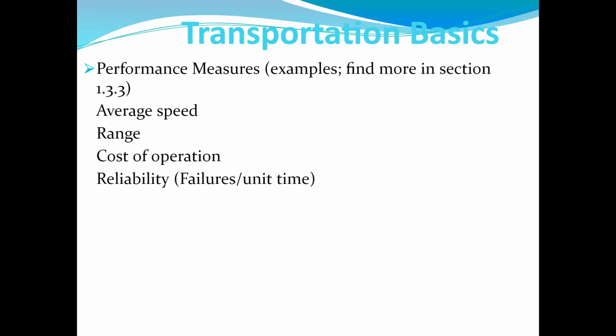So for example, even with the prevailing design philosophy, we allow for failures for 30 hours of the year because we design it for the 30th worst hour of traffic over the year-long period. And even that philosophy, as I said, is evolving now to be, maybe we shouldn't design it for even the 30th hour, because that still might be a little bit of an over design that leads to higher speed and less safe operations during other hours of the year. So these are interesting things that we'll talk about again in the future, but I just wanted to give you a flavor of that. Okay, with that, I will conclude this lecture.